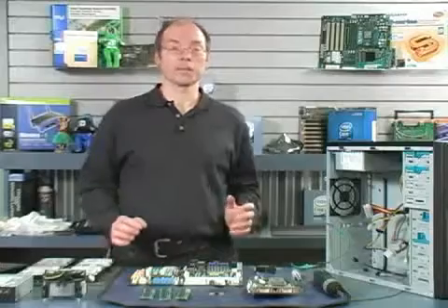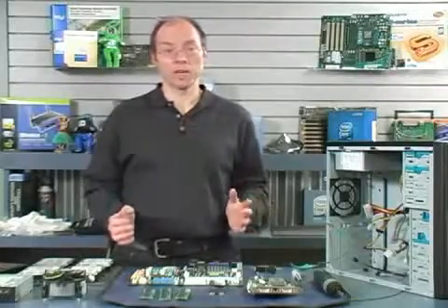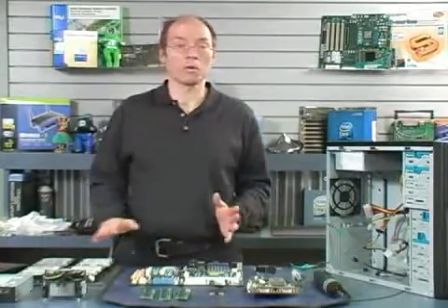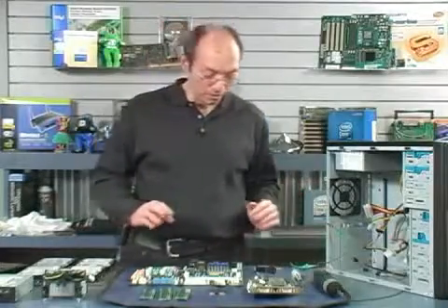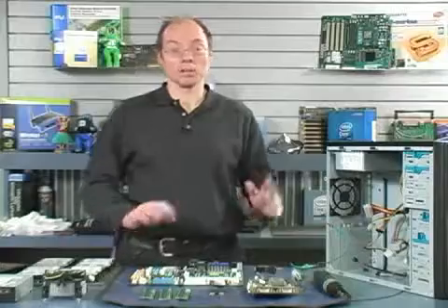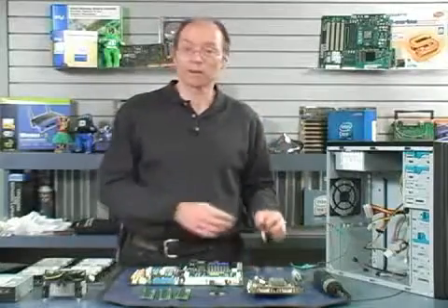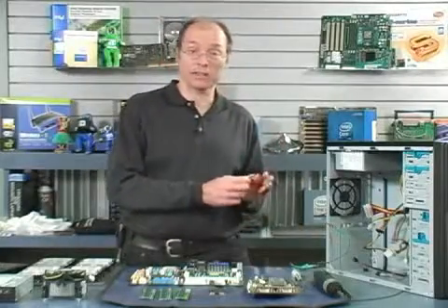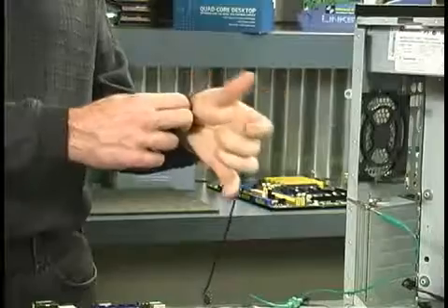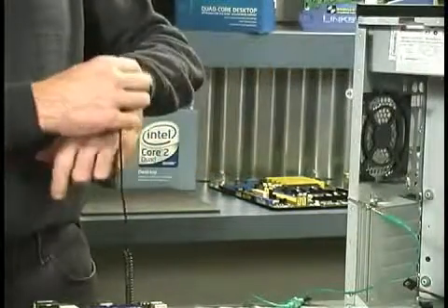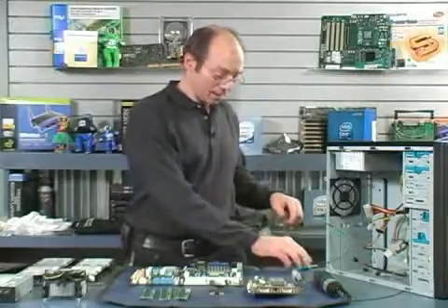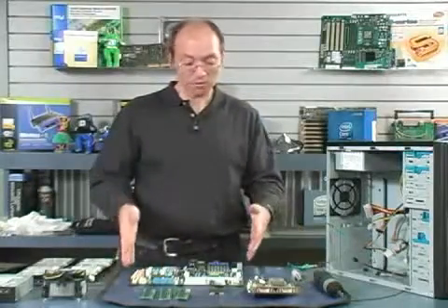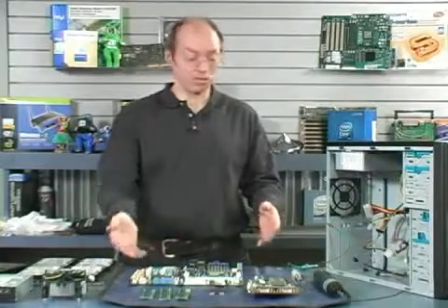In this series of segments, we're going to build a PC from scratch. Now, I've started by laying out all the components I'm going to use, and let's go over a few tips and tricks before we get started. Number one, to do things by the book, you should wear an ESD, electrostatic discharge protective wrist strap. So I'm putting that on here, and I have it connected from my wrist to an anti-static mat onto which I've laid out the motherboard, video card, processor, and RAM.